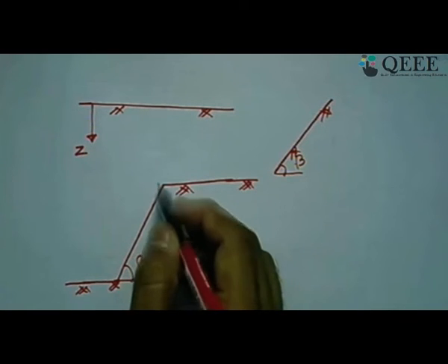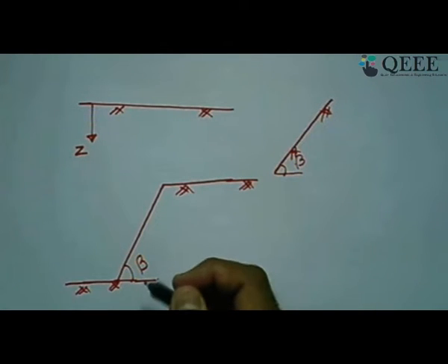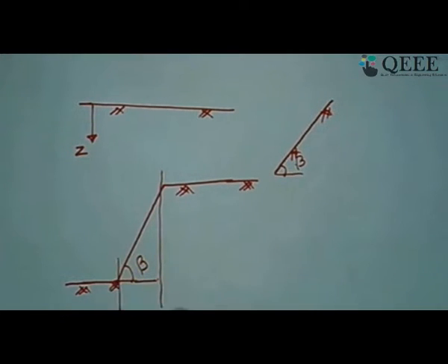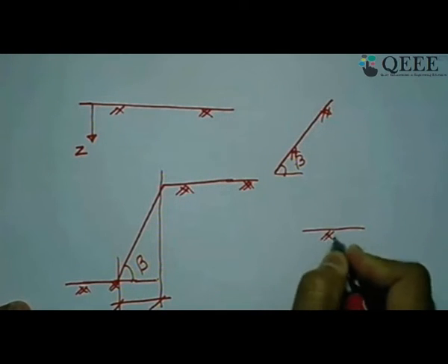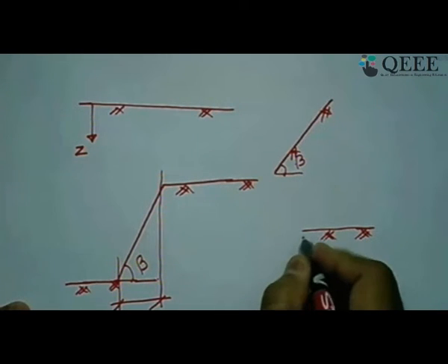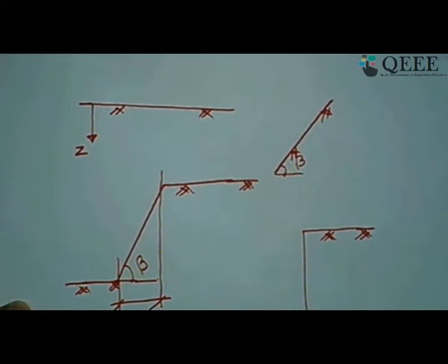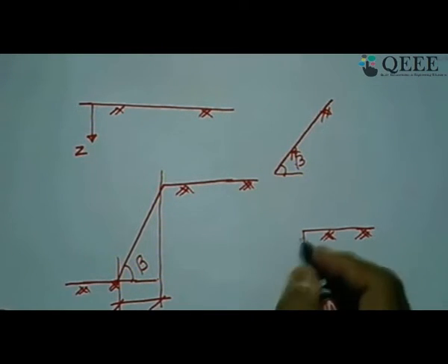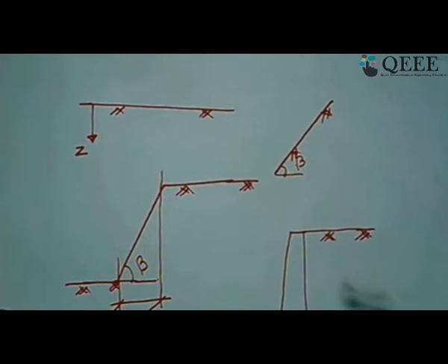But due to the limitation of the available space, in many cases, and mainly in urban areas where there is a severe space crunch, we cannot have this much extra space. This is nothing but an additional space required to have the stability of this inclination. So what can we suggest in such a case, if we want to maintain the same level height where there is a severe space crunch? To maintain this kind of two-level difference of ground surface, we need to provide some kind of supporting system here which maintains the stability of this level difference adjacent to each other. This is nothing but what we call a retaining structure.